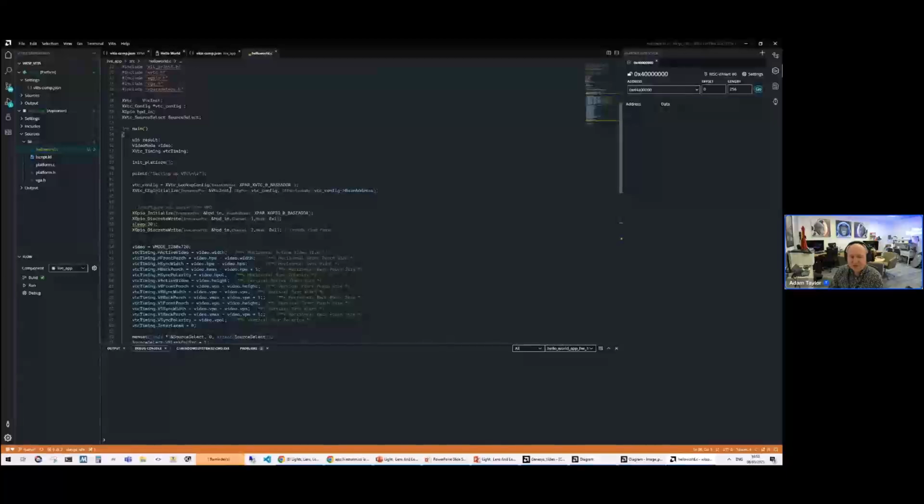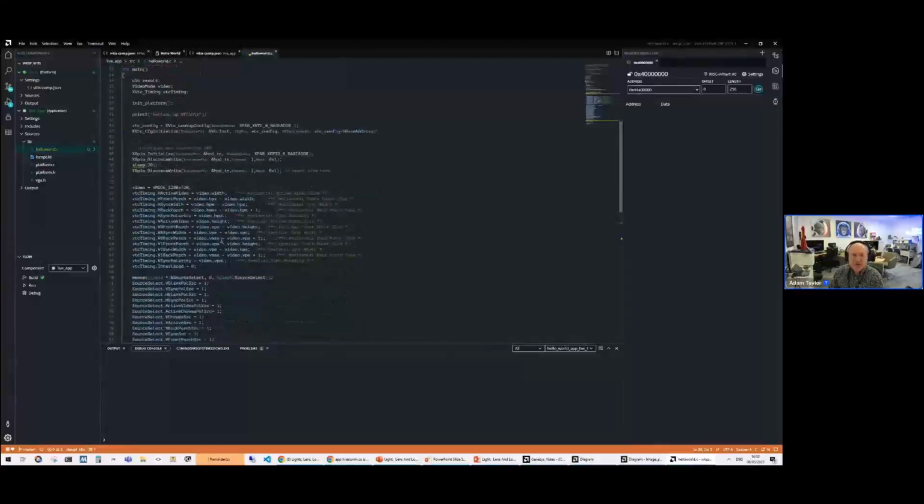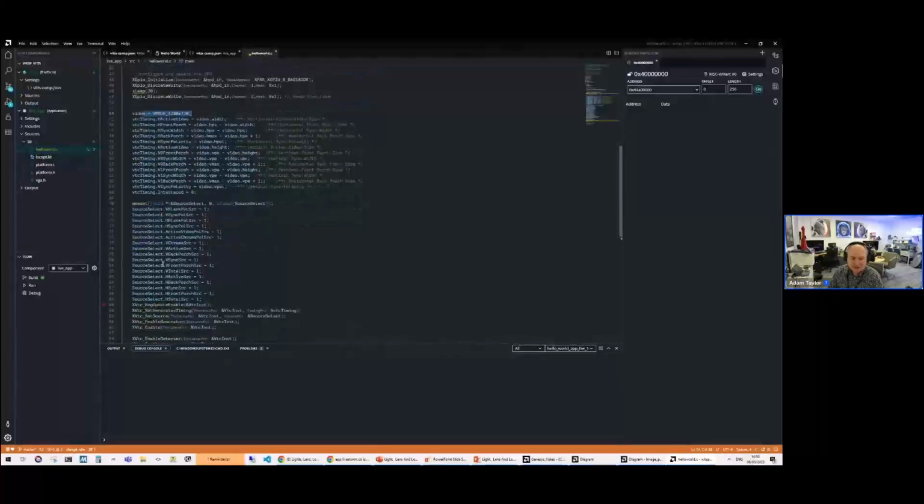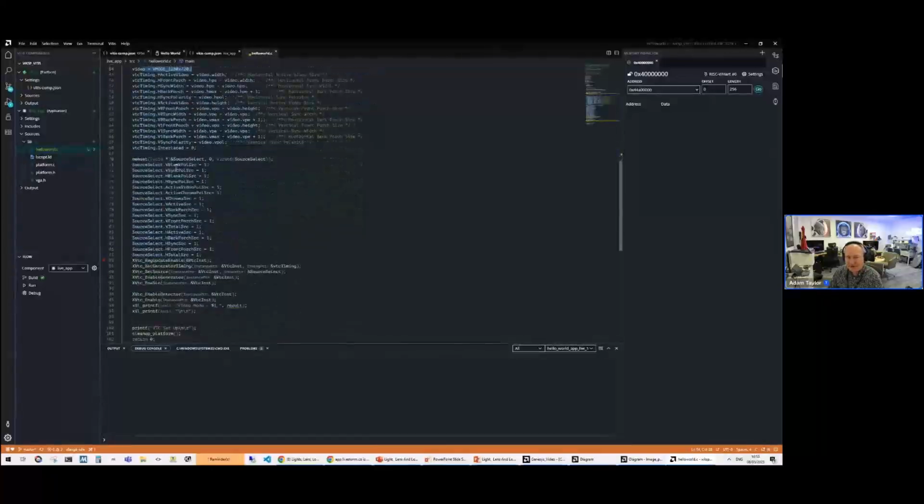So we pull this through, we configure the video timing controller lookup, we configure the AXI GPIO, we set the video mode that we're going to be operating in for the video timing controller. And then we set the source for the video timing controller as to where that's coming from. Then we update and allow the video timing controller to start both its detection and its generation.